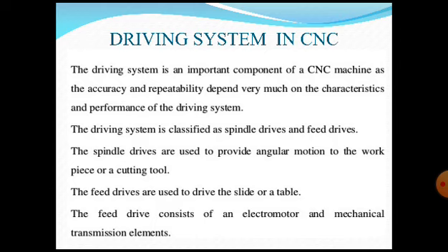The motor is going to provide you the rotational movement. That rotational movement has to be further converted into linear motion, especially for the table. Otherwise it needs to be controlled by a specialized driving system. That is what we call a stepper motor or a servo motor. Sometimes we also call it a servo mechanism.